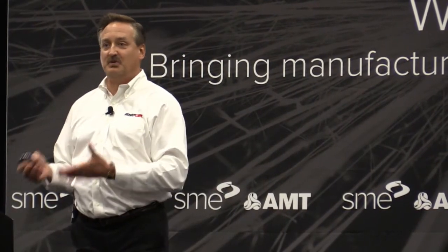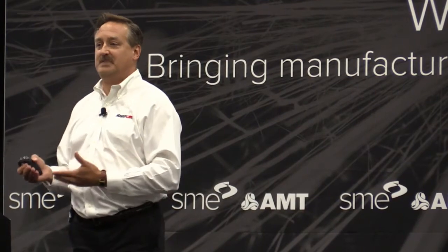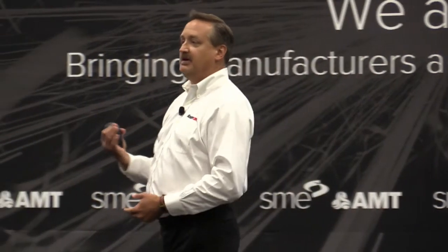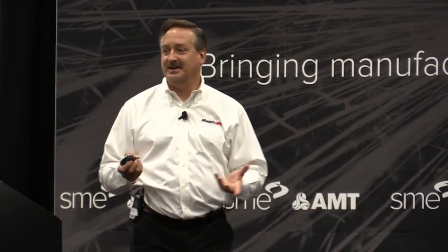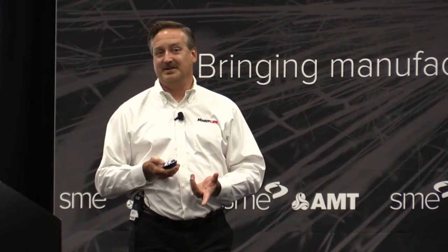So they're giving you specs for worst case scenarios. They're anticipating that you're potentially running older style, offset-based toolpaths, and you're going to be burying that tool into a corner here and there. So they back off their recommendations to make sure you're not going to kill their tool, and they want to maximize tool life. Makes sense, right?